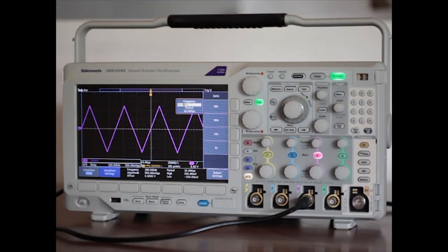When this is done, another menu appears on the right side of the display, permitting the user to select the desired units. Another soft key on the right allows us to choose amplitude and offset of the AFG waveform. These values again determined by multipurpose knobs A and B, or by the keyboard.